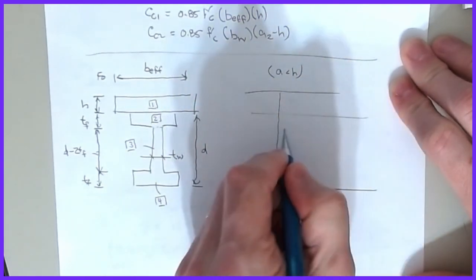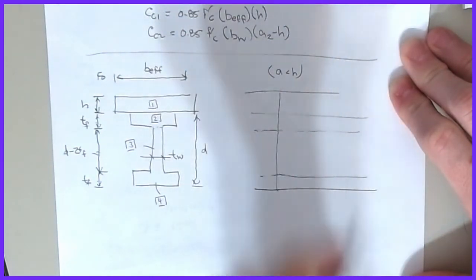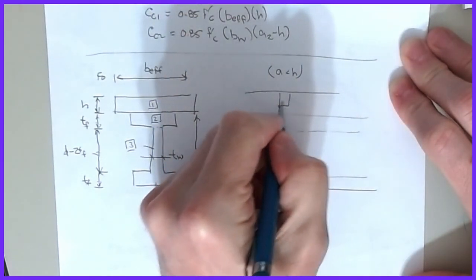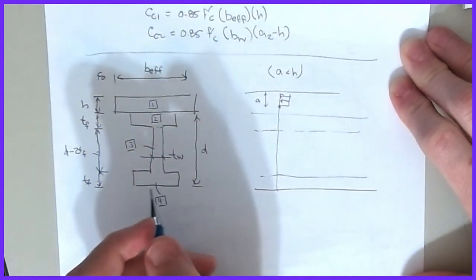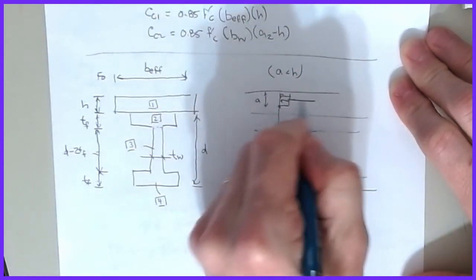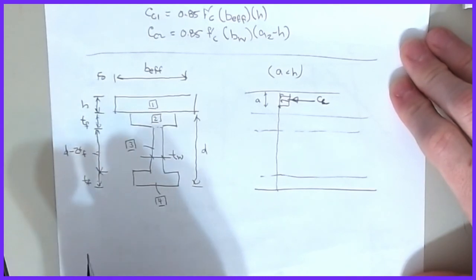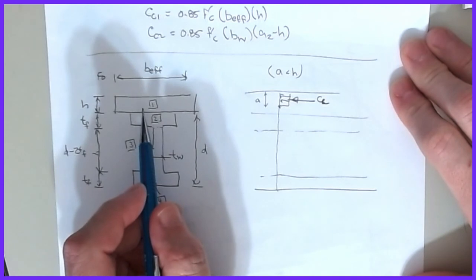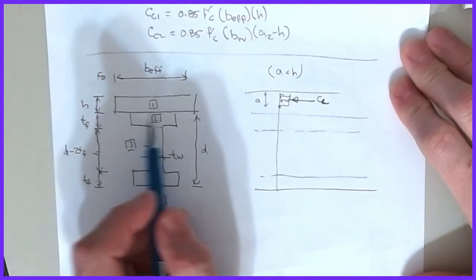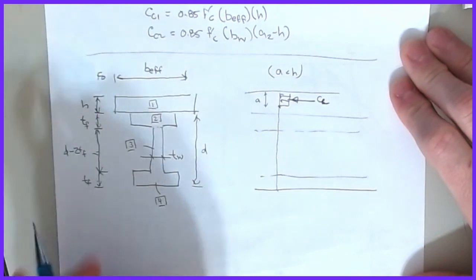that diagram that we build looks something like this. The concrete block goes to here. That height is A, right? And then, so that gets me our compressive force in the concrete. And then what happens is that whereas in the reinforced concrete case, we neglected tension in concrete, the steel beam, I can't do that, right?